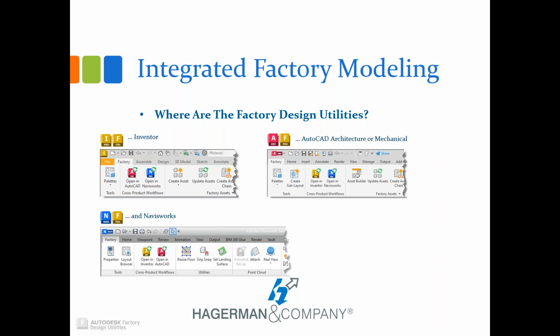And so what happens when you select one of these, from the Inventor side, it will take the 3D models that you've shown and it will create a flat view of those and open it inside AutoCAD Mechanical. If you started in AutoCAD Mechanical and you're using the factory utilities and assets, and you select Open in Inventor, it will prompt you to save, and then launch Inventor and open that model for you on the Inventor side and show you the 3D form of those assets that you were just looking at on the 2D side. And then if you want to take either of those over to Navisworks, it will take that 3D model and present that there inside of Navisworks for you.